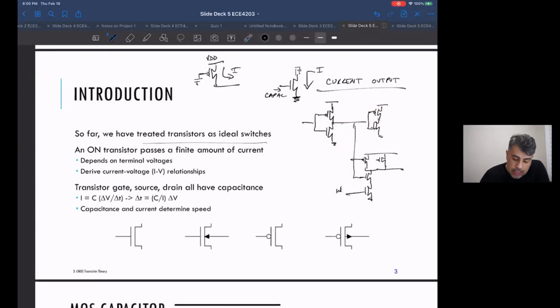Okay, and what does that look like? So I'll always have to write this down. When you're putting charge into a capacitor, you get this kind of equation for charge and voltage. And if you want to see current, you take the derivative with respect to time of both sides. So dq/dt by definition is current. So if you want to see dV/dt, it is I over C. What's dV/dt? Okay, when we're talking about rise time.